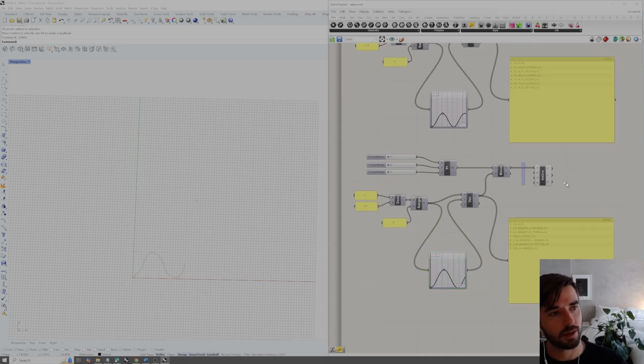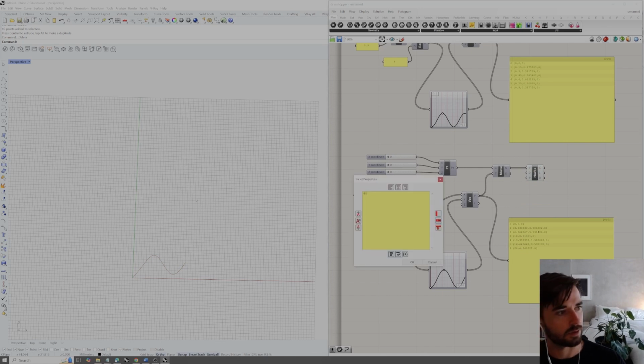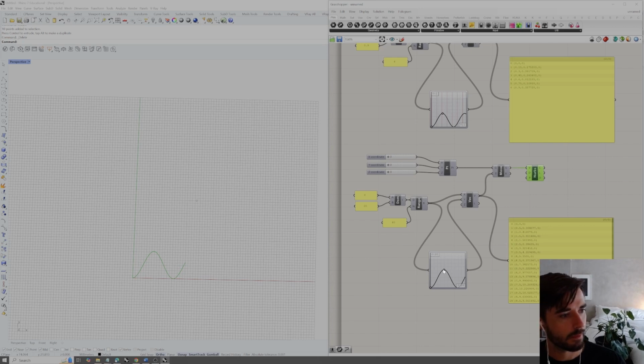And now instead of that interp curve, I'm going to change this back to a NURBS curve, which will be degree 3, and then we can also change this back to 40 control points. And now as we make this edit, we have a much larger curve being drawn out in space.